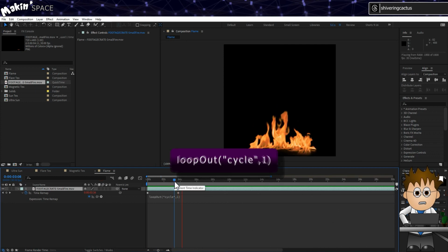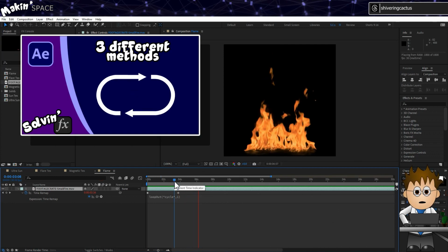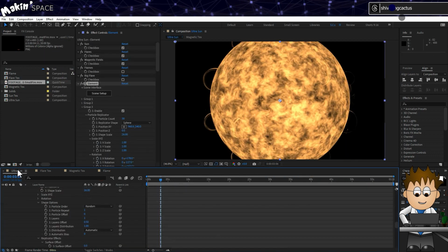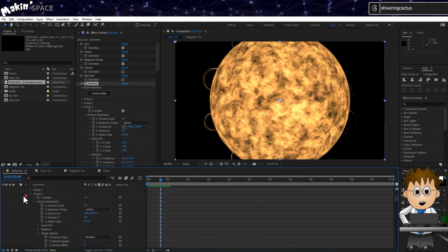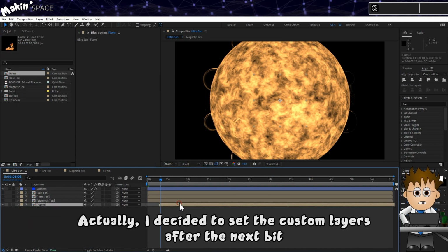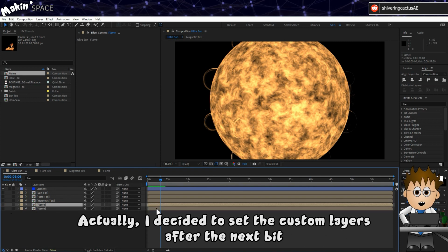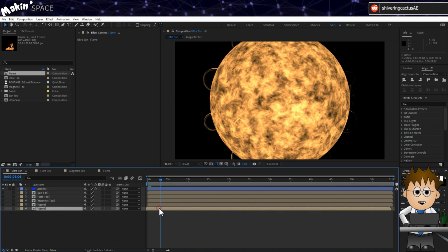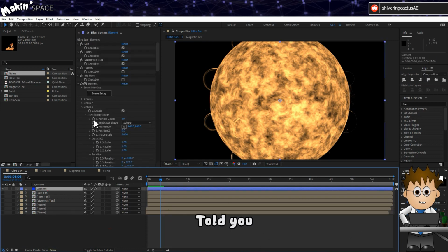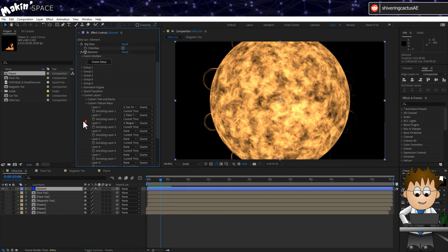The 1 tells After Effects to look at the last keyframe and the previous one for the cycling animation. Now, it's not perfect, and I shared a tutorial about creating a perfect loop from footage, which is linked in the description. But I think it's fine for our purposes. So next, drag this comp into our main comp, turn it off and set it as a custom layer. But then duplicate this comp twice and shift their starting points a few frames. And add these as their own custom layers.